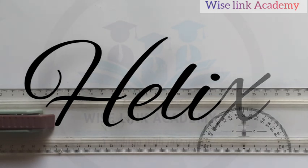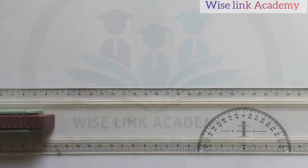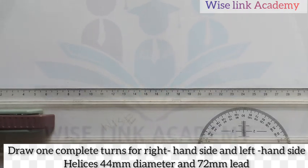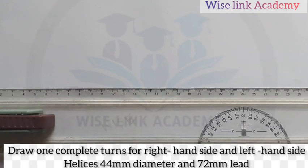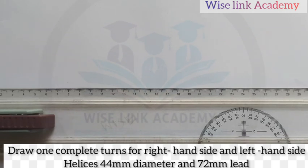Here's a question below. Draw one complete turn for right hand and left hand helices, 44 mm diameter and 72 mm lead. Now, from the concept of helix, note something please. Whenever you hear the word lead, it is also called pitch.